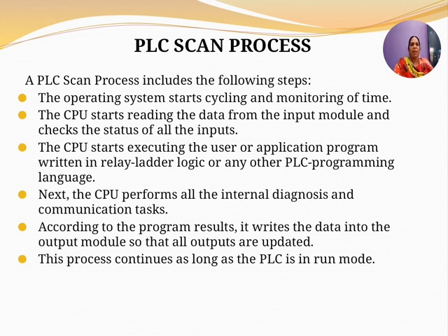So what is actually happening? A sensor or a device converts a physical condition into an electrical signal, which can be either a discrete or analog signal, digital signal or analog signal. These are given as input to the central processing unit. The CPU makes the decisions and issues control instructions based on the memory resident program, and the output module converts the control instructions from the CPU into a digital or analog signal that can be used to control various field devices, that is the actuators.